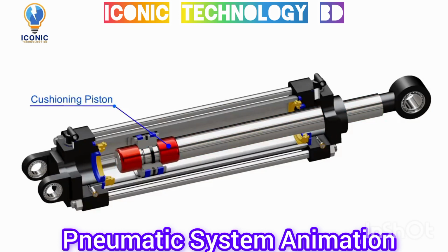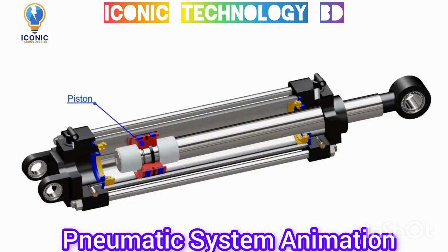These pistons prevent any hard shocks at the end of the stroke by enabling the piston to stop slowly and gradually. The piston reciprocates back and forth when there is pressure difference between any of the two sides. A static seal ensures airtight sealing between the piston and rod. Piston guide rings are assembled to prevent metal-to-metal contact of piston and cylinder. Piston seal provides airtight sealing between the cylinder and piston.